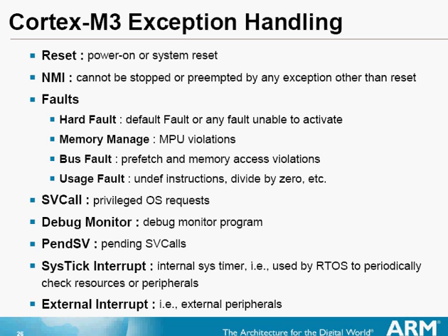Hard fault, any fault that is not handled by other fault handlers, meaning memory management fault, bus fault, usage fault, will activate this interrupt. The interrupt is also activated when the other fault handlers are turned off. So these 3 exceptions are unconfigurable.